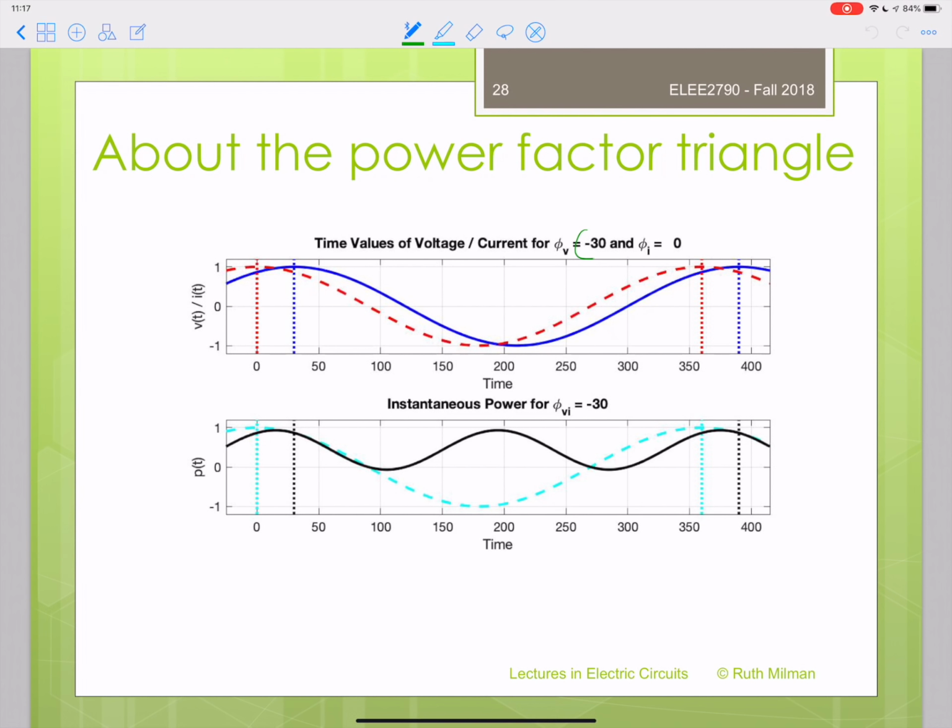Now, what we've done here is I continue to shift these over, so this is now a capacitive load. How do we know that? Because the difference in that angle is negative. So now what you actually have is a situation where phi I is greater than phi V, and as soon as phi I is greater than phi V, instead of doing what you did before and lagging, your voltage is actually leading. So your voltage is ahead. So now your voltage is leading. You see that angle right in here, and you see that there becomes an imaginary part.